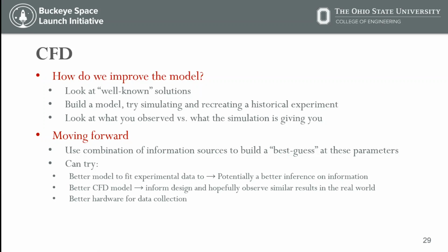And so, moving with that discussion of fins, maybe a reason that our CFD model was only about 10% of what we expected to see. Maybe the area of those fins greatly impacts the skin friction drag. And our CFD model didn't have any fins, so it wasn't capturing that skin friction drag. Not only that, but it's real life, so you get wind, so you could have drag off the fins. So there's just so much.